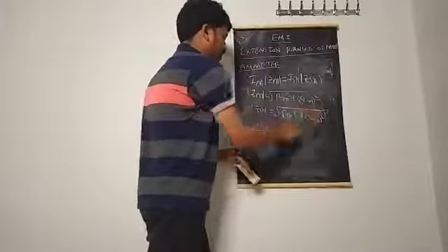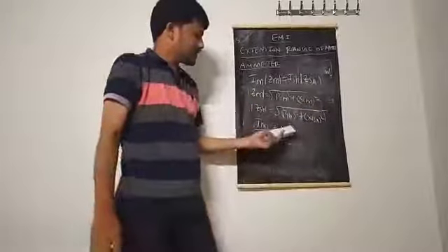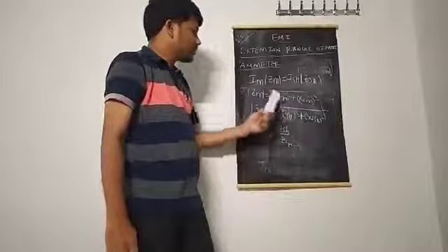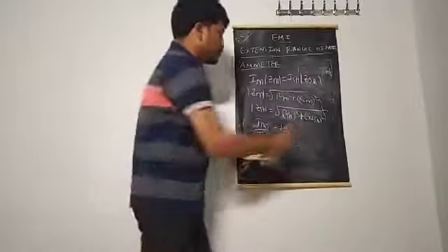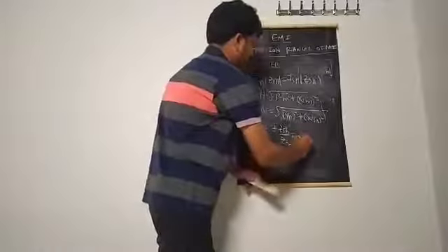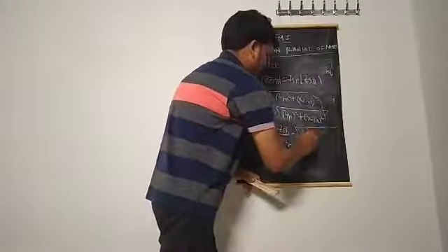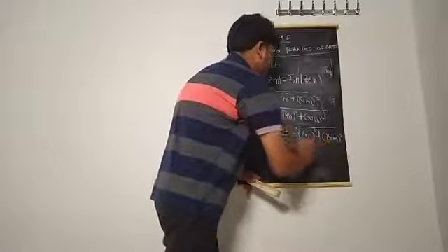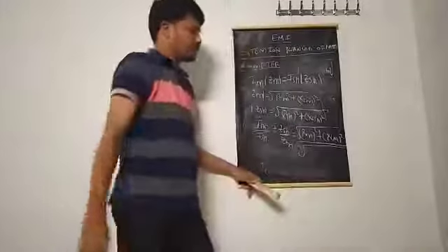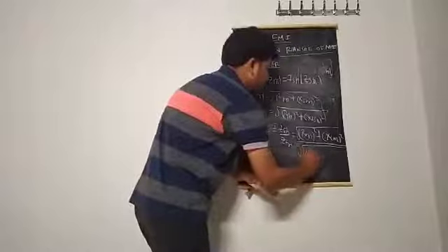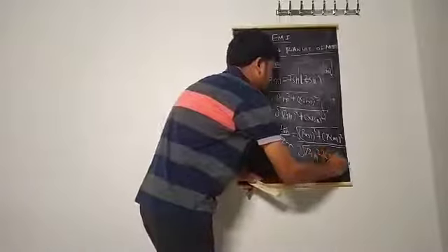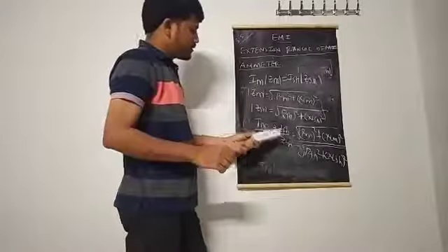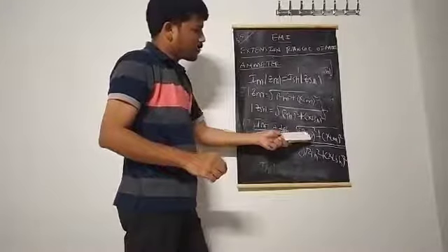So, from this, first let us write it like this: Im by ISH is equal to ZSH by Zm. What is ZSH? This equation. What is Zm? This equation. Substitute these above equations here. So, from this we got square root of Rm square plus XLM whole square by square root of RSH square plus XLSH whole square. Is it right? So Im by ISH is equal to ZSH by Zm.